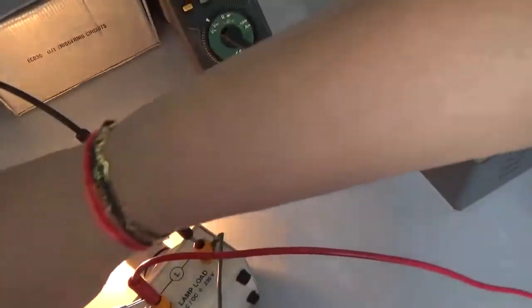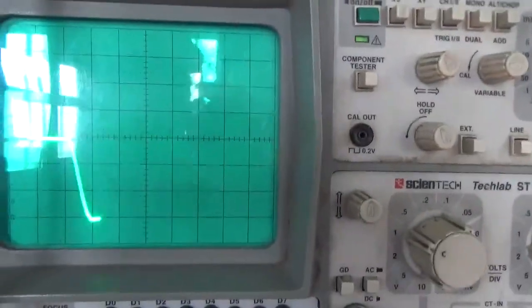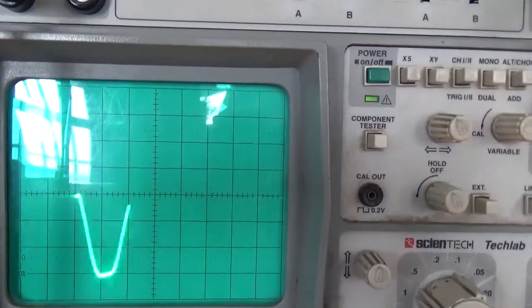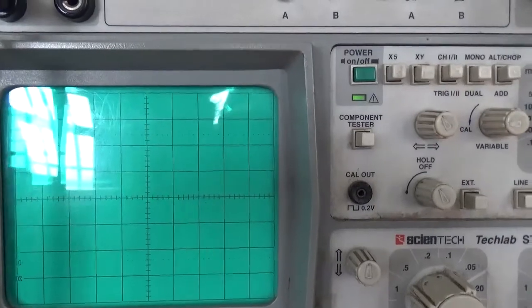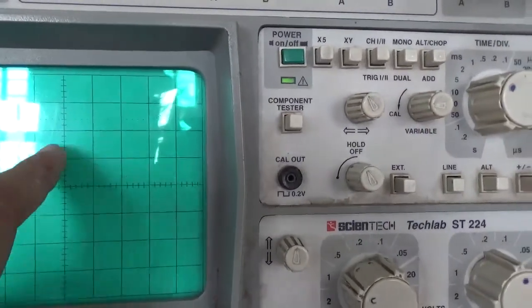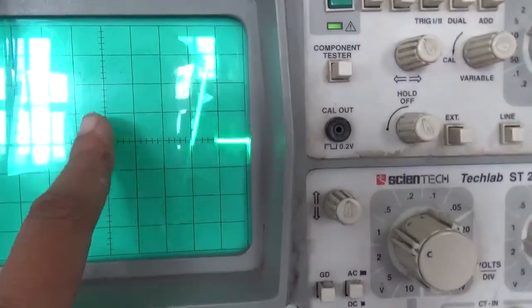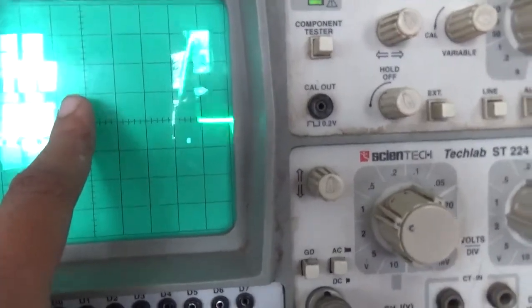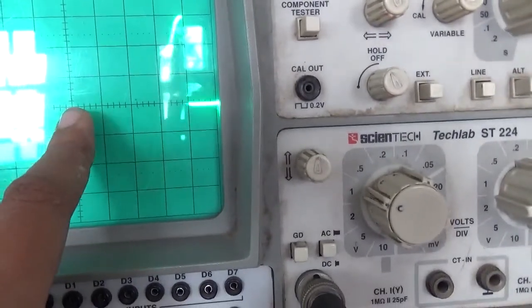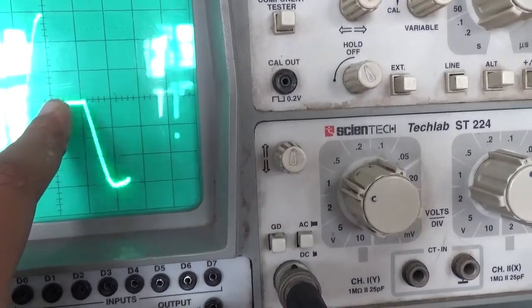Okay, you can also check alpha from the SCR. In the SCR, see, I have kept alpha at 90 degrees. What it indicates is that your positive cycle is covering 180 degrees. Until 90 degrees, the voltage appears across the SCR, indicating it is in the off state. At this point, the SCR goes to the on state.